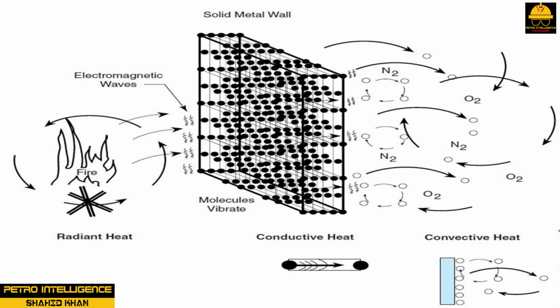The best conditions for heat transfer are large temperature differences between the products being heated and cooled. The higher the temperature difference, the greater the heat transfer, high heating or coolant flow rates, and a large cross-sectional area of the exchanger.